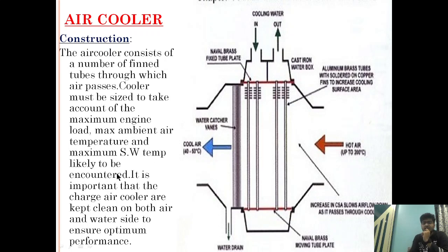So if anybody asks what things we should take into consideration while choosing a cooler, you should say we will take into account the maximum load of the engine, the maximum ambient temperature, and the maximum sea temperature, meaning where it is going to operate. These are the criteria for choosing an air cooler.